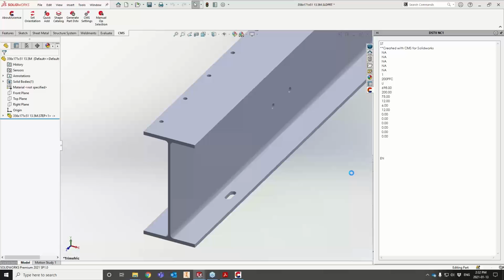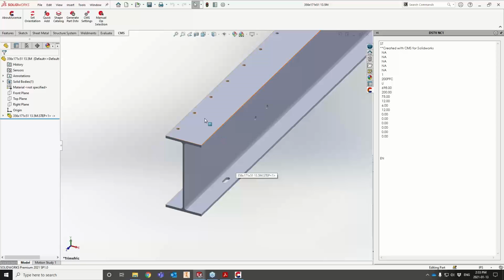So you just save it, and then the drill is exactly the same as your SLDPRT, because even though you are opening a STEP file, at the end of the day you are working on just a simple SLDPRT, right? That doesn't contain any features, just a solid body right now.